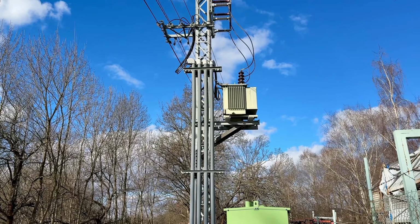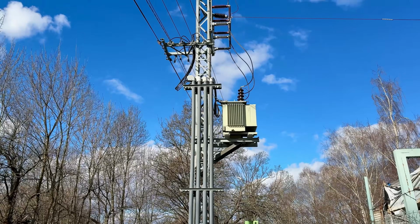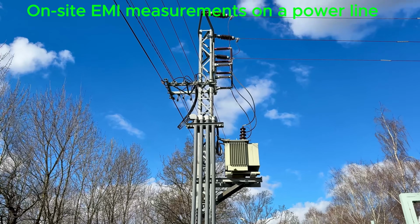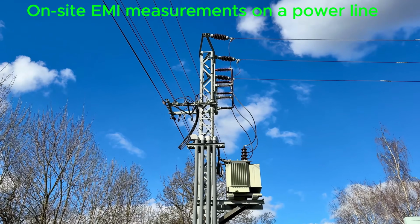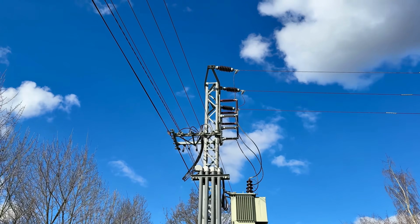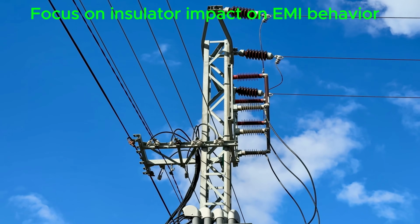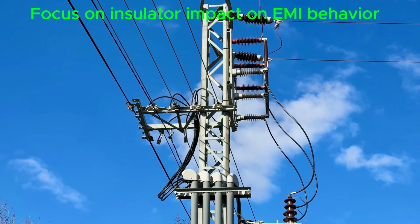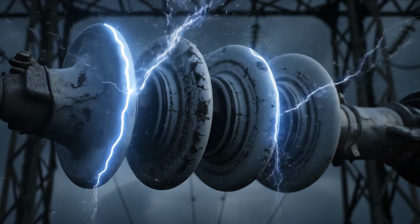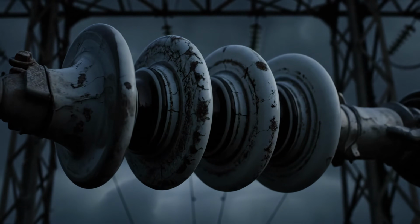In this video, I'll walk through a short EMI measurement summary from recent on-site testing, focusing on the behavior of an insulator installed on a power line. Although an insulator is a passive component and doesn't generate signals on its own, our measurements show that it can significantly influence conducted and radiated electromagnetic noise on the line.